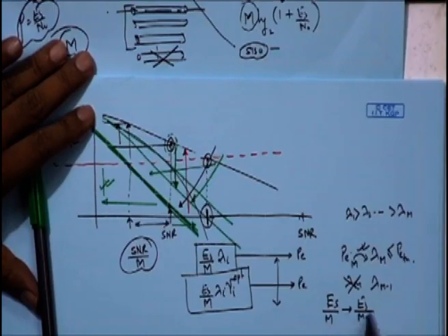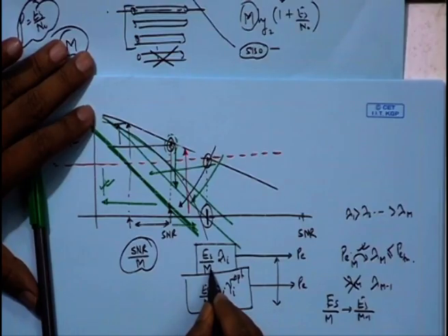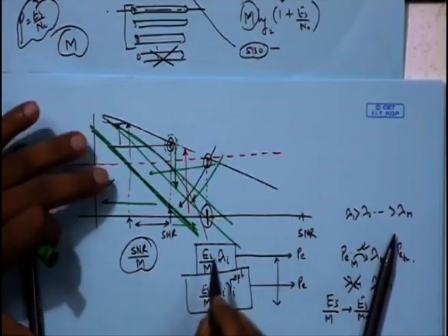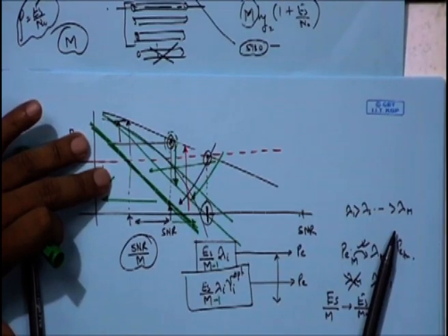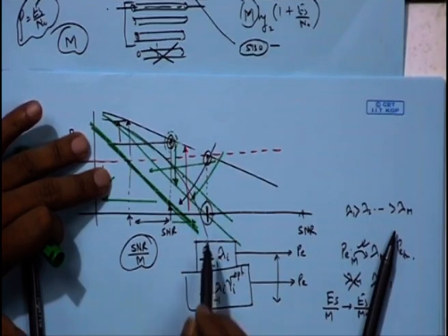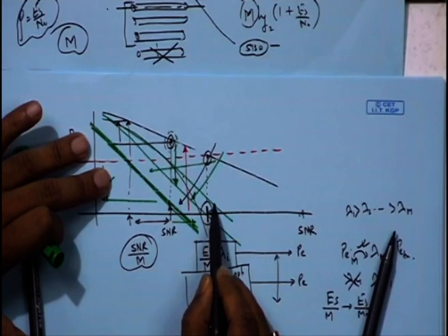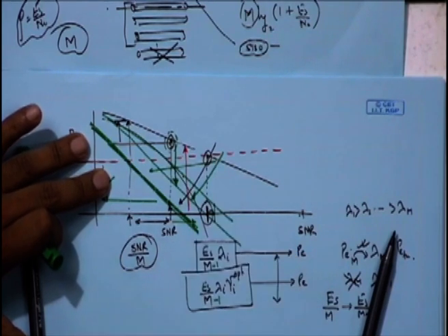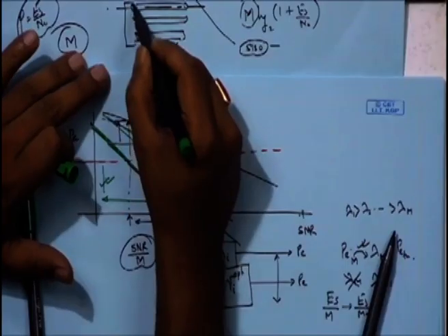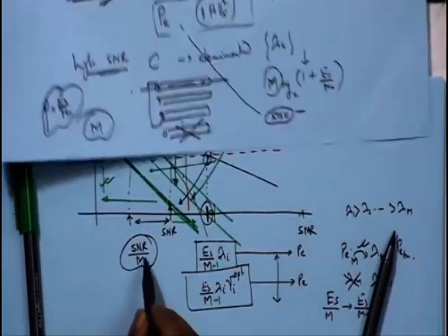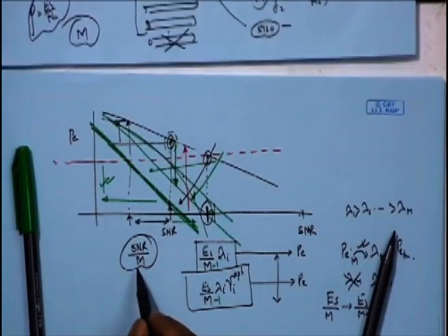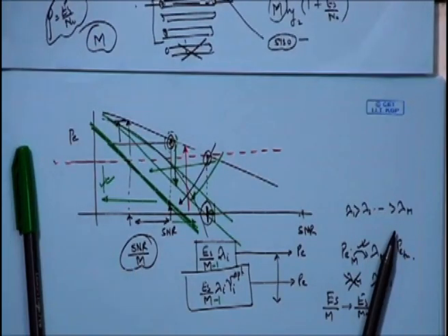Each of the branches is going to have extra power, so the average SNR of each has increased. Even this point has shifted here, and the error probability then might be satisfied. So, we will be using a lesser number of streams than would be allowed by these M antenna branches. Basically, there is a trade off which we can do.